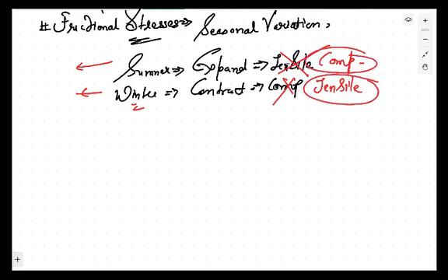Now, we know that the tensile stresses are developed in winter, and the concrete is critical when tension is developed, because the concrete is a brittle material. That's why winter is the critical season where there can be failure of the slab. Now, how the failure? Because there will be the development of frictional stresses. Frictional stresses will be developed at the bottom of the slab, when the slab tries to expand or contract.